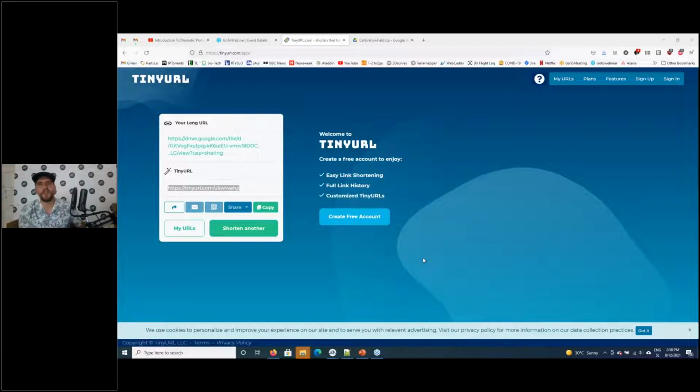Yes, I would recommend you first do a calibration project. You can do calibration the same way we did it for drones. You can put some targets on a facade and then record images of these targets from various angles in order to get the best calibration parameters. Alternatively, you can also use this calibration field. Both of these things will work.